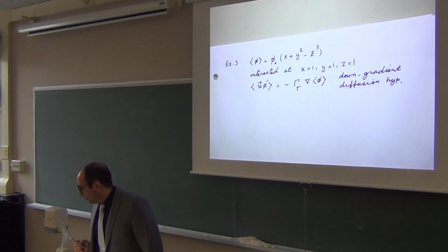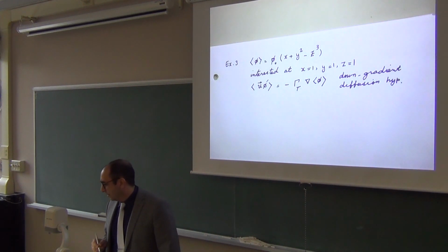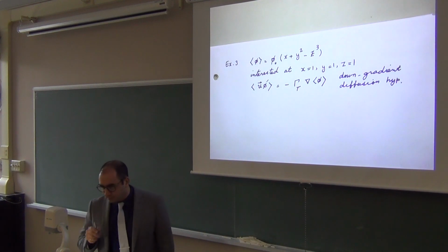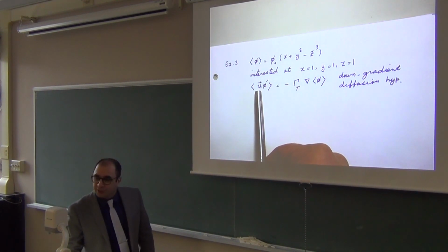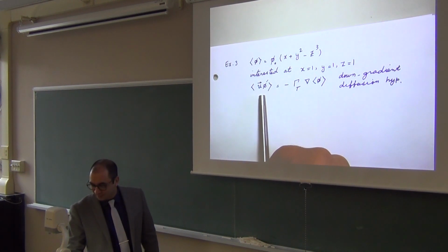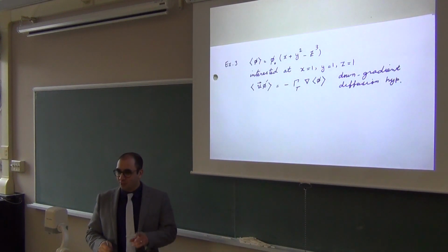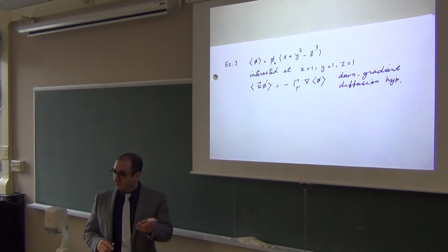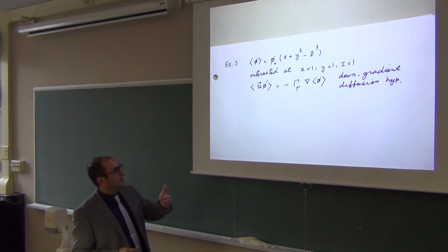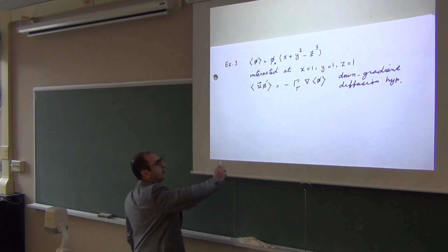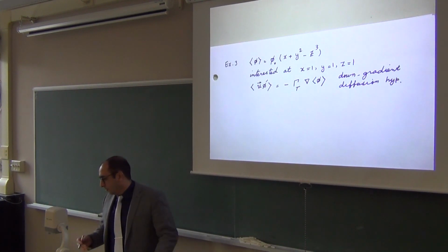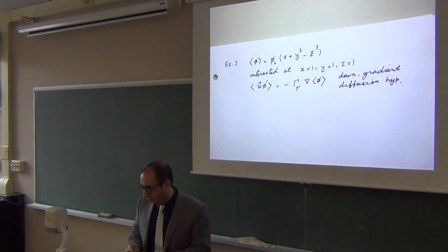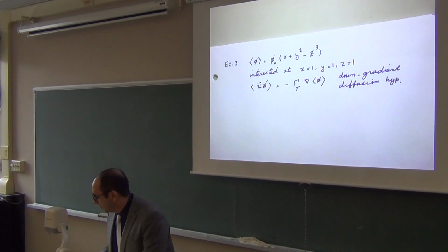Okay. Now we should calculate this turbulent flux vector. Remember that, be careful. I have put vector u here. What does it mean? It means that I'm actually looking at three fluxes, right? I mean, I could talk about flux in the x direction, flux in the y direction, and flux in the z direction. So actually, I'm showing three equations to you, if you will. Of course, you could tackle them one by one. That's fine. But I just showed all three equations together.